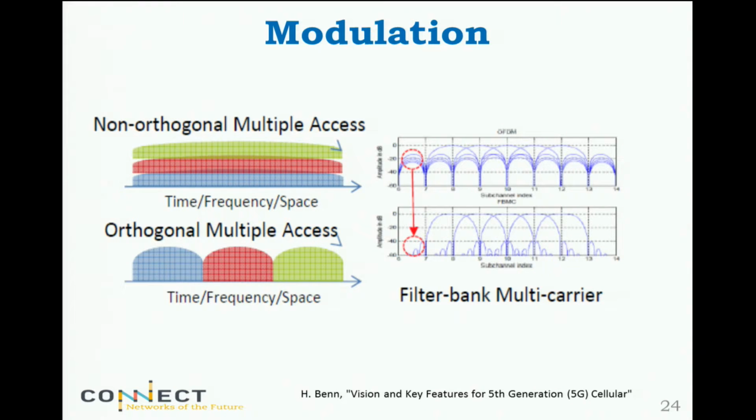That's right. That's the natural option. You can do other things, but raised cosine is the first thing I would pick, right? So what happens then is that the decay in frequency gets quicker. For example, with raised cosine, I think the decay is 1 over f squared, right? So you definitely decay much faster, okay? In essence, that's what they try to do.